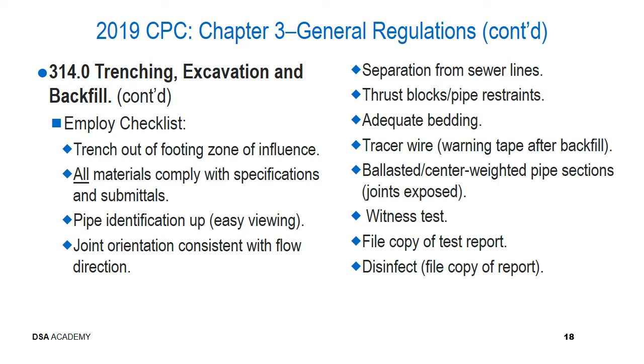Also, the bedding. You want to make sure that the bedding material that was delivered and the backfill material comply with the specifications and subsequent submittals if applicable. So, with respect to the trench itself, the first thing you're going to review, after the geotech report, is make sure that the trench is located outside of the zone of influence of the footing for the building that it's next to.